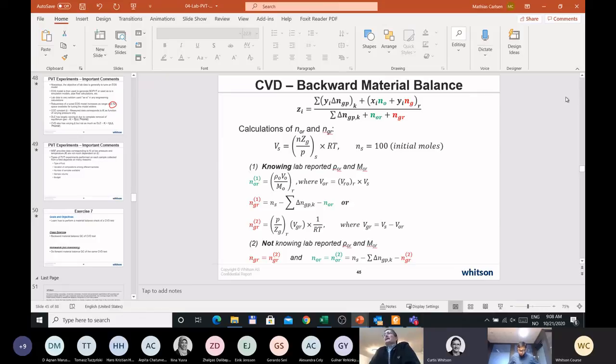And for the gas condensates, the CVD removed gas compositions are very, very important to getting right and to modeling correctly. So all this compositional material balance checking is to ensure that what we are tuning and matching with the equation of state are proper data, particularly the amount of heavies, the barrels per million